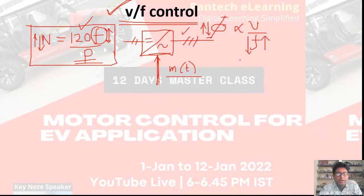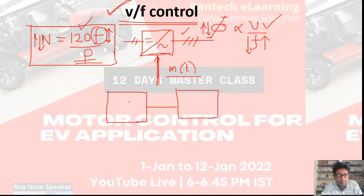So to maintain the flux level constant and also to change the RPM, to the extent we change the frequency, to the same extent we need to change the voltage. So if I reduce the frequency by half, then I will reduce the voltage also by half, so that the flux is constant. Okay. So to do so, one power electronics arrangement is used. I am telling all the classical concept.